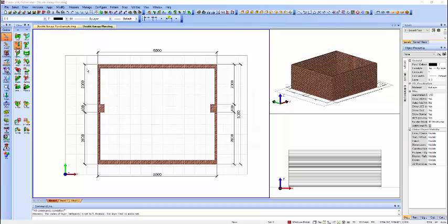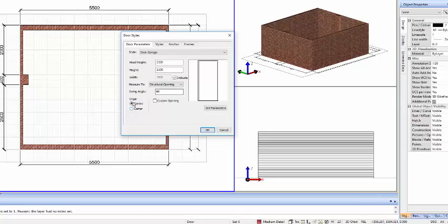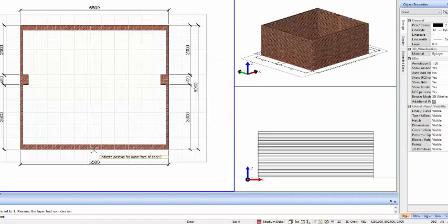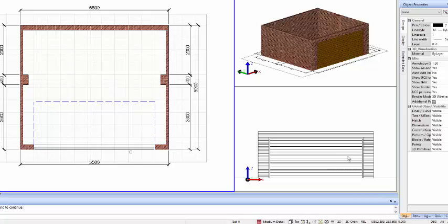We'll now add in the doors. So here we have a garage door, so this is an up and over door. We're going to indicate it based on the centre moving outwards. So we'll just choose the centre of our wall here and then to the edge of the door, and we can just toggle through till we get the opening that we wish.